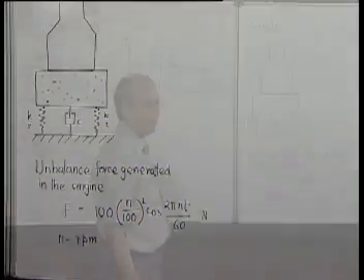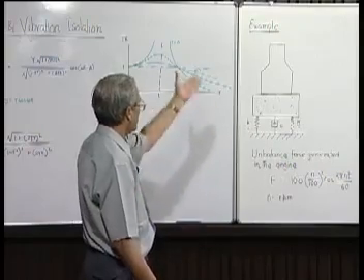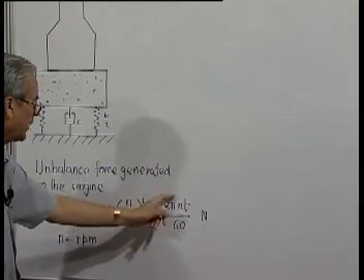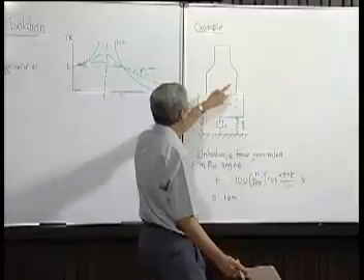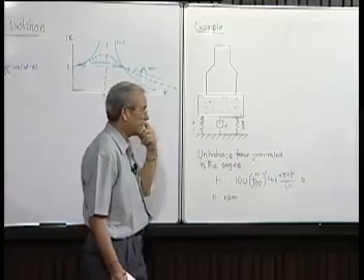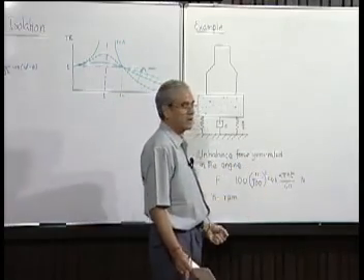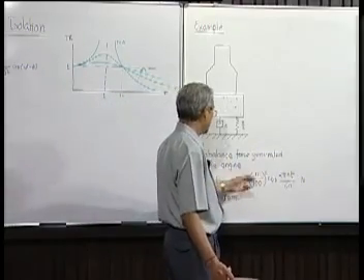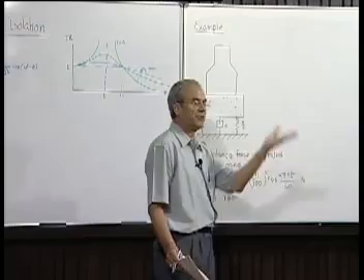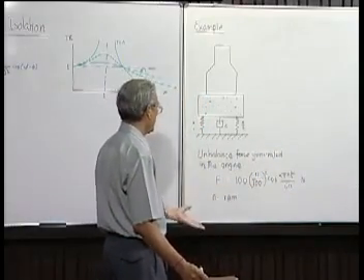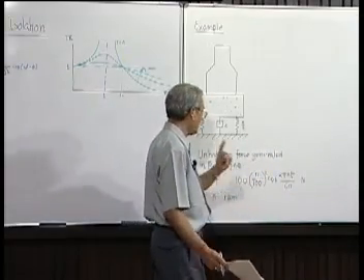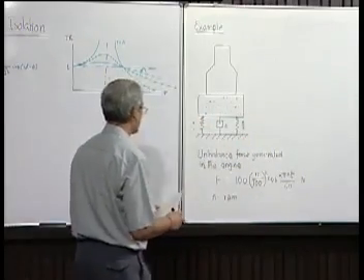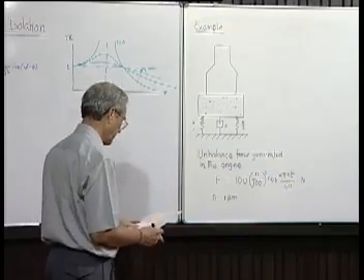So, this is a simple harmonic force. We are assuming that it is the primary unbalanced force. That is why it is 2 pi n by 60 t. That means it is omega into t. That means it is connected with the rotational speed of the engine, and therefore, it is clear that it is the primary. And the magnitude of the force is also increasing with speed, obviously, because the centrifugal force or unbalanced forces will always be increasing in magnitude, not only in frequency, when the RPM increases. So, this tells us the approximate representation of the generated force.